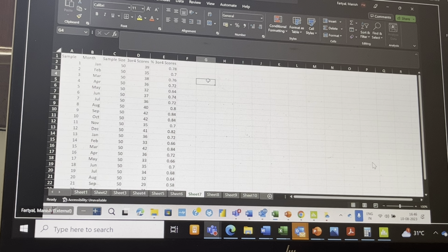Yes, sir. So tell me which control chart. Is it data on defects or defectives? Defectives. NP chart, sir. Very good. NP chart, because the subgroup size is constant. You are asking only 50 customers. So maximum how many customers will be satisfied? 50. So it is data on defectives, boss. Why are you getting confused? So copy C and D.